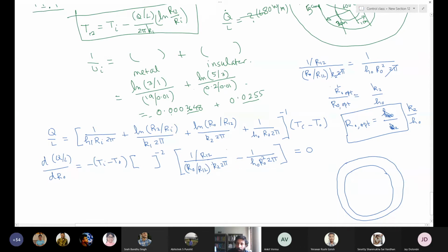We'll assume that the metal wall resistance is not important, and also the thermal conductivity of the metal is not given, so the metal wall resistance has to be neglected. This side temperature is 77 Kelvin. They also say that no temperature gradient exists in the liquid nitrogen, so the entire liquid nitrogen is at 77 Kelvin. So the wall temperature at this end is 77 Kelvin.